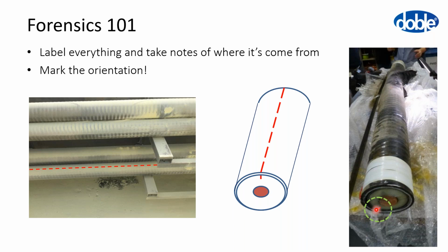So yeah, even potentially put a mark on the insulation. The insulation shouldn't move inside the metallic sheet, but I've seen examples where the cable core is actually quite loose. So again, just put a mark on the insulation such that it lines up with the mark on the top of the cable, or the bottom, or however you're going to label it.